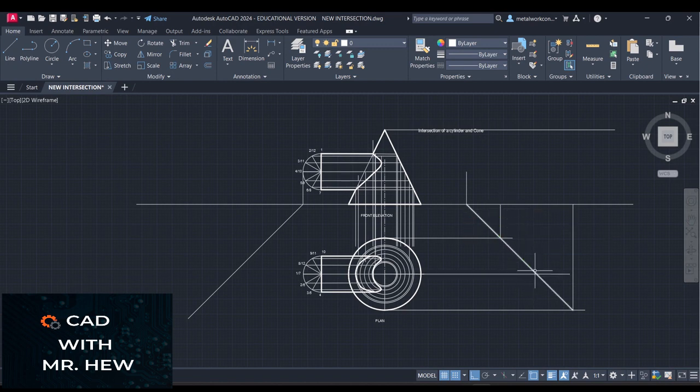We're also going to carry the center line going up to the baseline there. This line would go straight up to the top there because that's the top of the cone. Now we're going to draw the sloping sides to get the side of the cone. All right, so that's our cone.